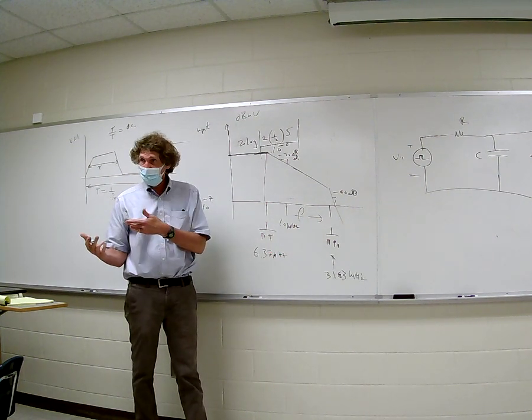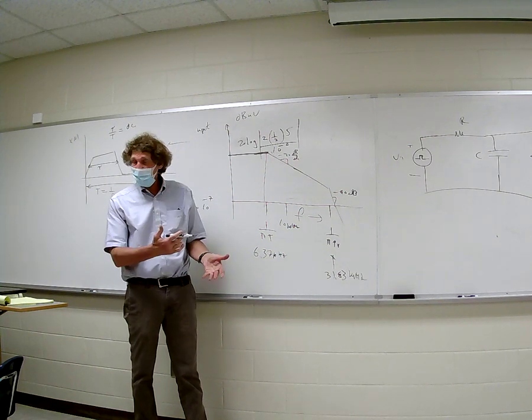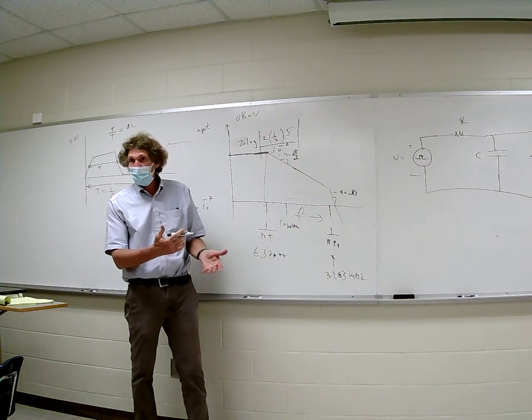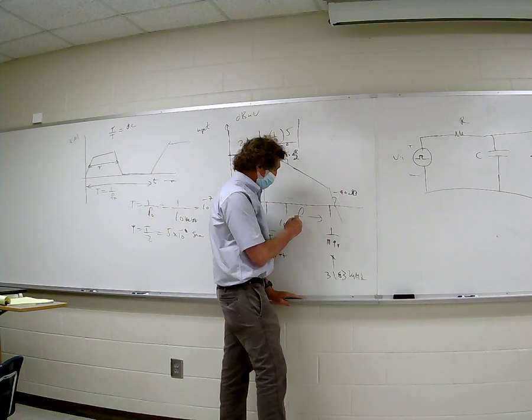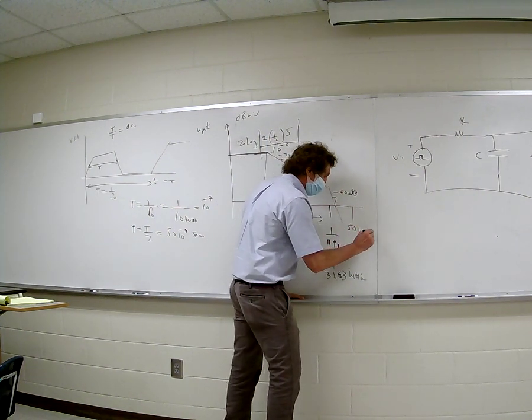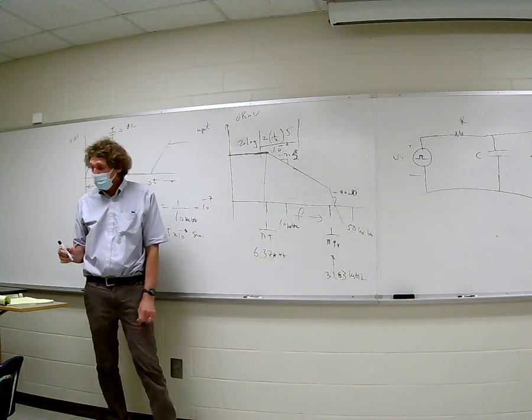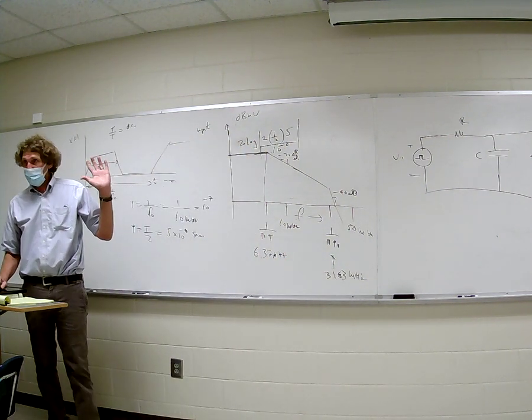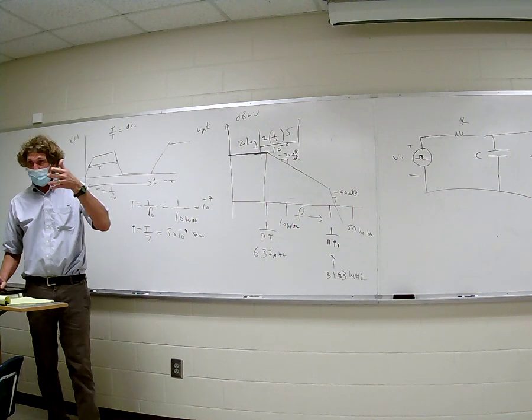That's what I should have said right from the start, because we've already calculated the dB reduction of the filter, right? So what's that going to be? Well, the 5th harmonic is out here. That would be 50 megahertz. Do you all agree with that? You with me? I'm not trying to go fast. You got me on this?